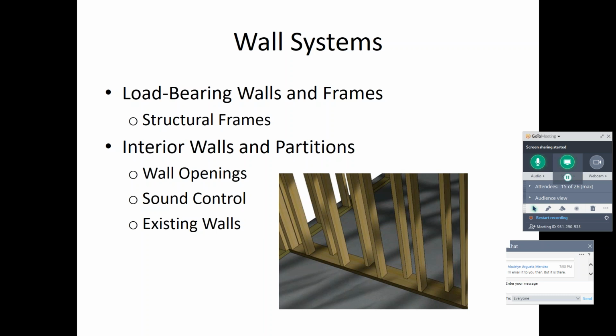We have load-bearing walls that are predominantly, not only are they centralized or dividing it up into equal portions, but they're mostly made out of concrete masonry, and they're usually at least reinforced with metal or doubled up. So we have them being pretty strong against the things that we were talking about earlier, like tensile strength and compression issues. Openings such as windows and doors are going to have big impacts on the load of the structure. That's why we saw the lintel before, but it also has an impact on what type of materials are used and how we can reinforce them outside of something like a lintel.